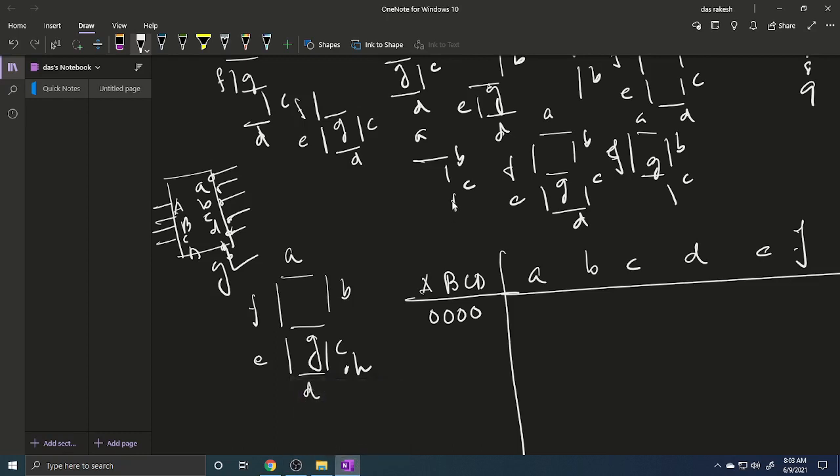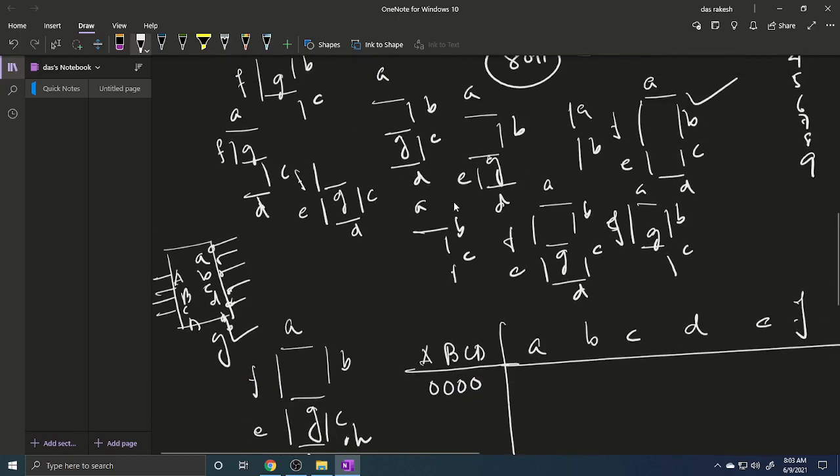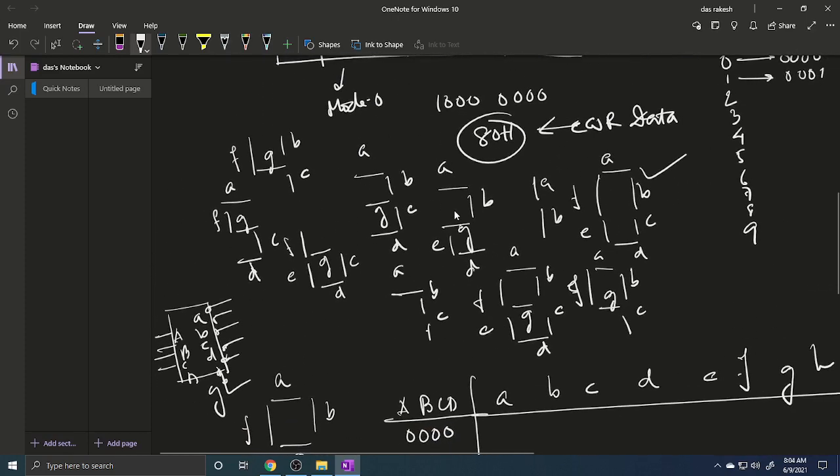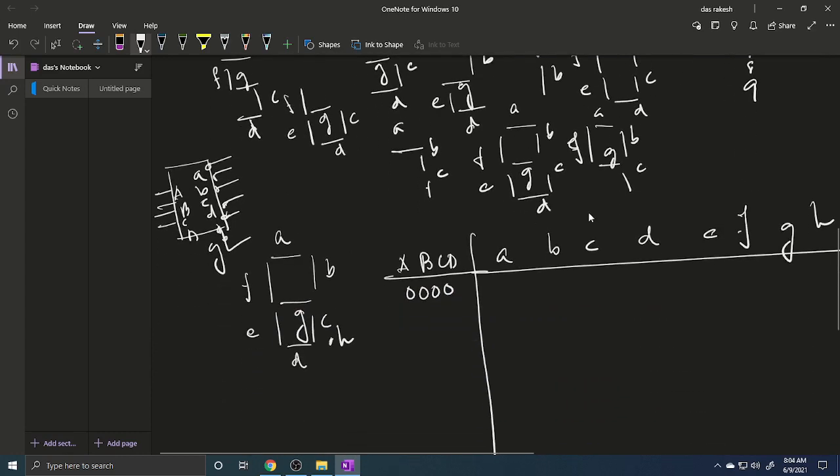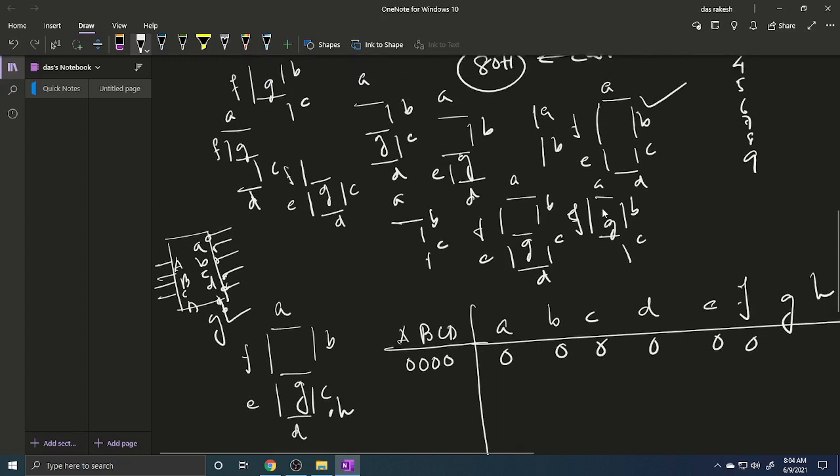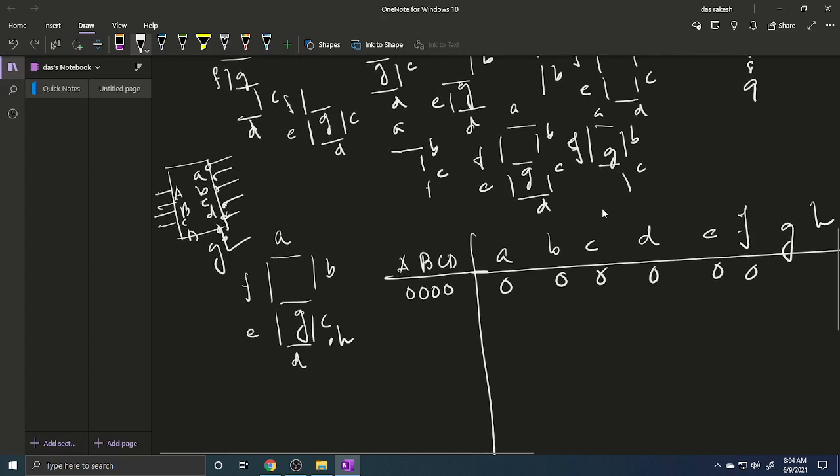Okay, so now when this ABCD equals 0 0, that means this segment is for A, that is A, B, C, D, E, F, all bits output are equal to 0, because this is a common anode type. E, F, not G and H. If H will be on, then H equals 0, otherwise this is off.